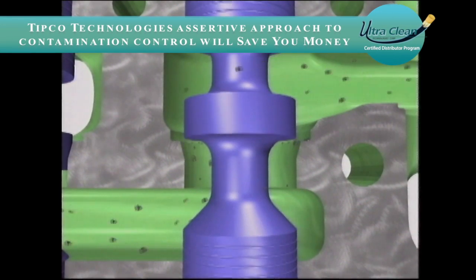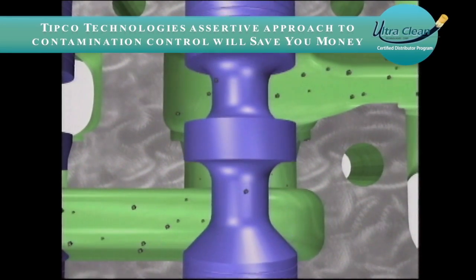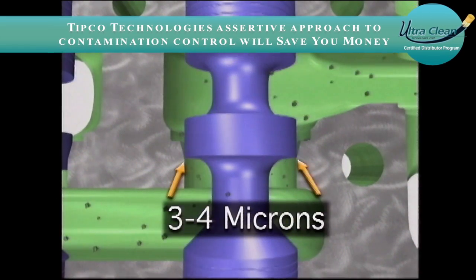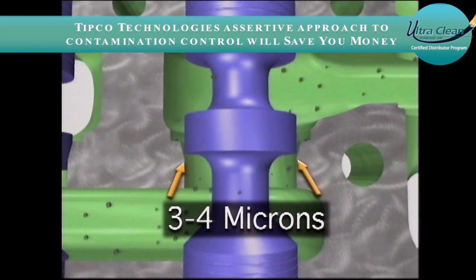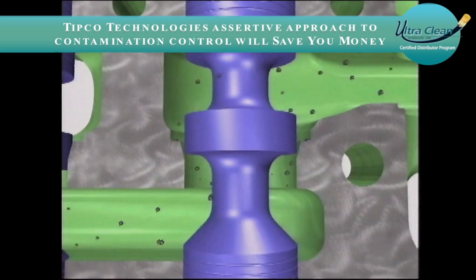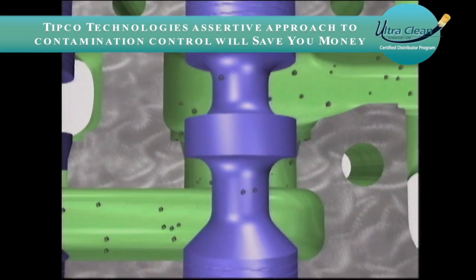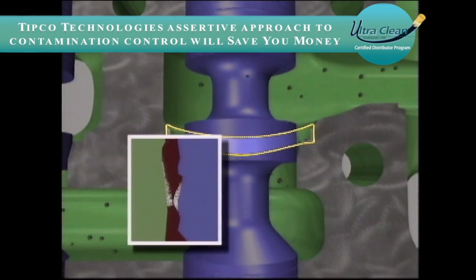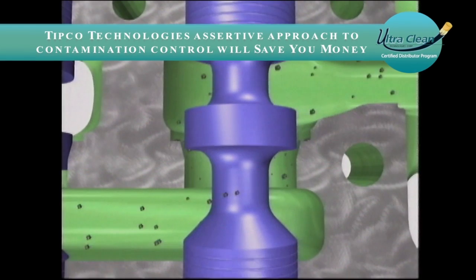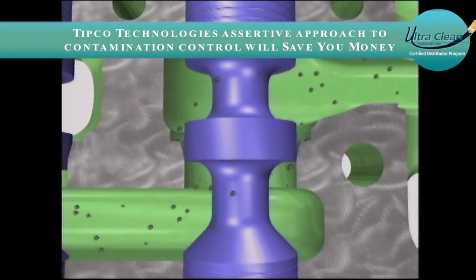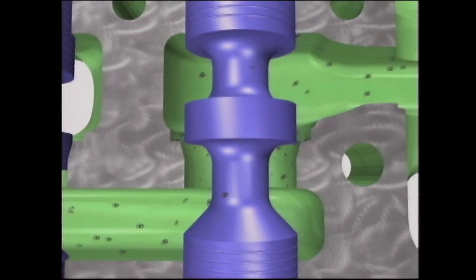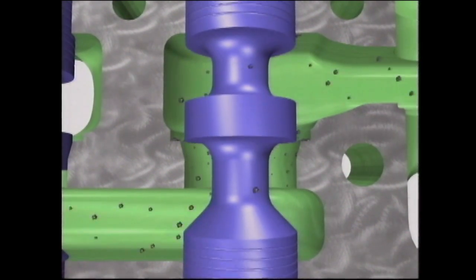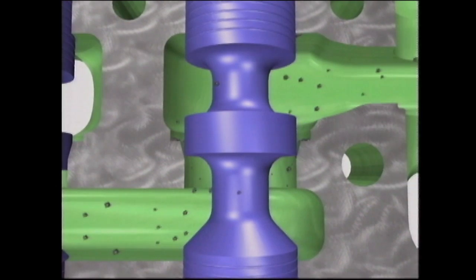Electro-hydraulic valves are more susceptible to contaminant damage because the clearances are even smaller, as small as 3 to 4 microns. Some of the particles naturally adhere to the imperfections in the wall or because of the electromagnetic conditions in the valve. This buildup, or siltation, can either slow the spool, causing sluggishness, or make the spool hesitate, causing jerkiness in the system. Over time, the contaminants can cause wear on the spool that results in leakage, and sometimes a large particle can become lodged and block the motion in the valve.